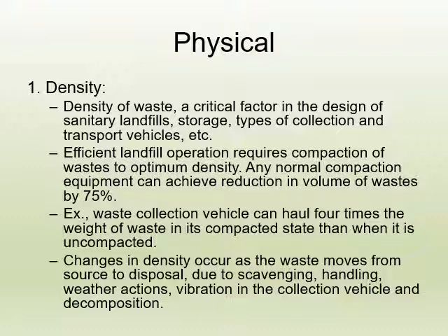So compaction is needed. Any normal compaction equipment can achieve a reduction in volume of waste, so it will densify it by up to 75%. For example, a waste collection vehicle can haul 4 times the weight of waste in its compacted state than when it is not compacted.